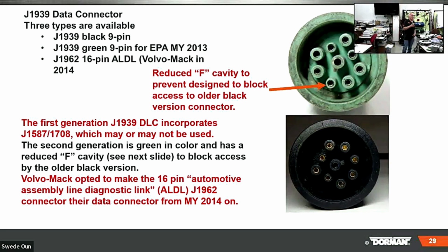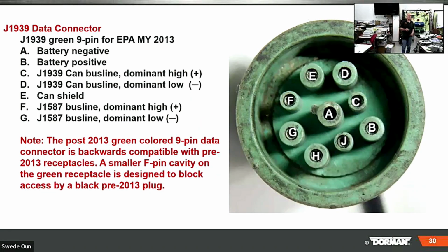Volvo Mack opted to make the 16-pin automotive assembly line diagnostic link their data connector from model year 2014 on. And we'll put it into perspective here. So here, in case you wanted to, is your pinout. I even threw that in if you ever wanted to go in and back probe and look at your CAN issues and everything else.